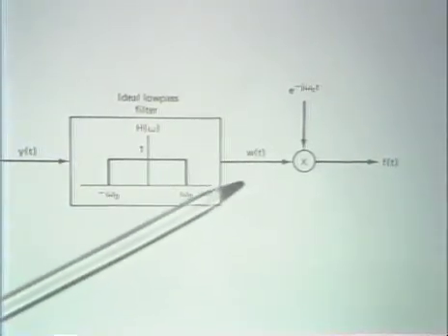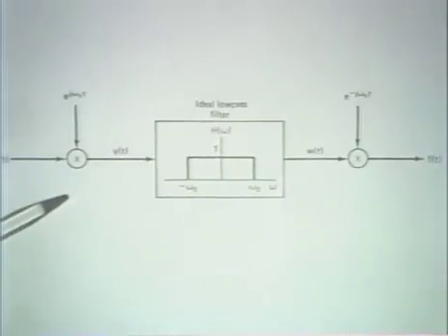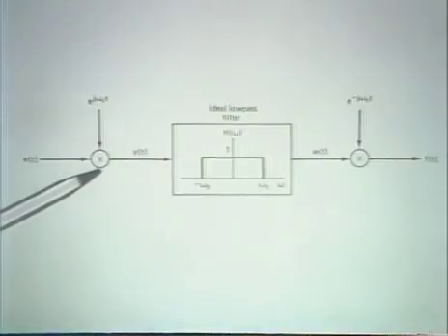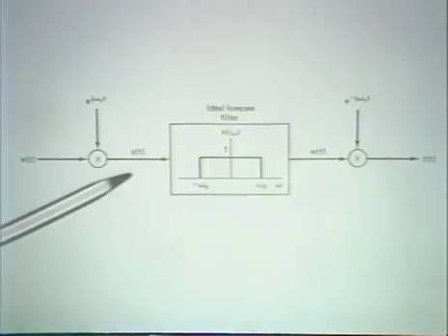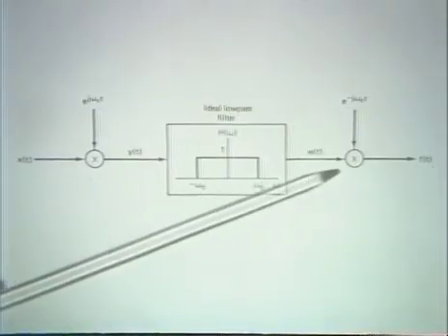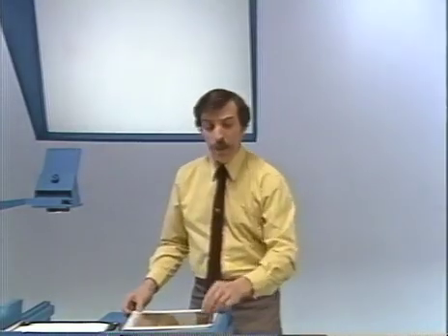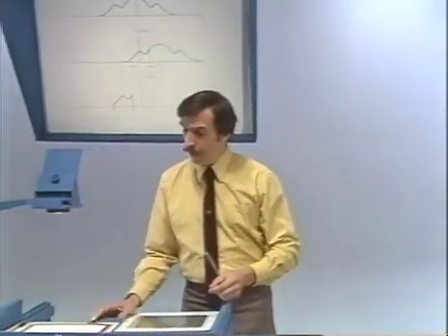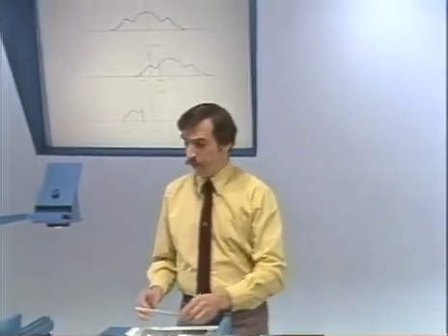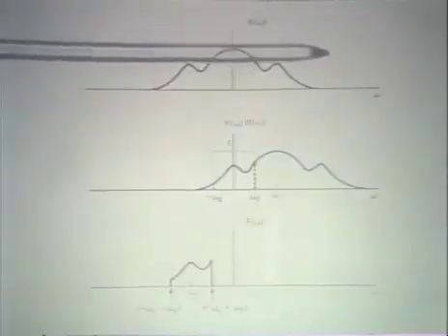Then, in fact, what we've done is to take the spectrum of the input signal, shift it, pull out what is now around low frequencies, and then shift that part of the spectrum back to where it belongs. So if we look at that in terms of actually tracking through the spectra, we would have initially a spectrum for the original signal, which I show at the top as X of omega.